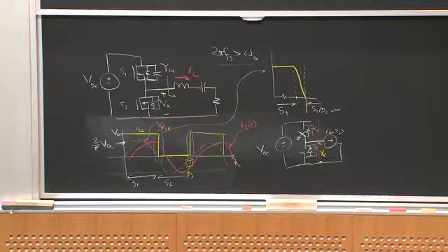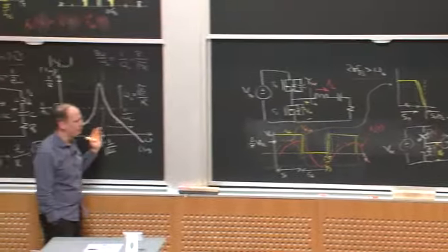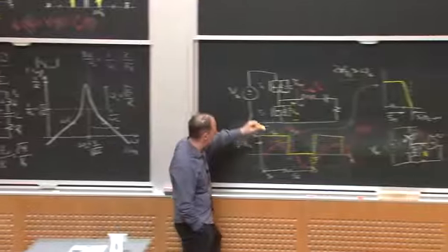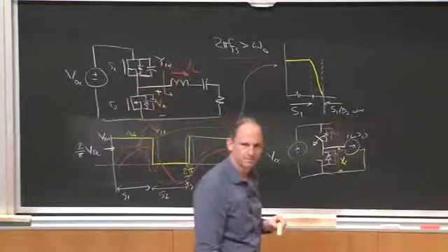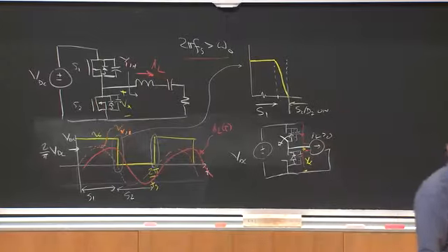Now it turns out if I wanted to go the other way, I could actually do 0 current switching. If I wanted to operate below resonance, I could do 0 current switching. But we're often not interested in that, because with 0 voltage switching I can get rid of losses associated with the device capacitor switching. Okay? Questions about that?